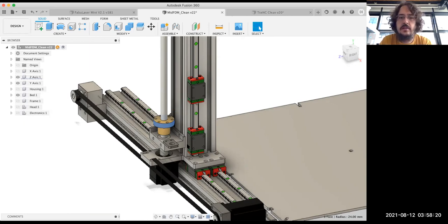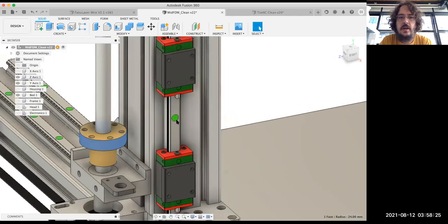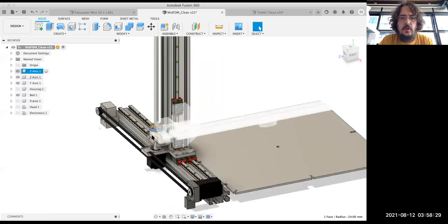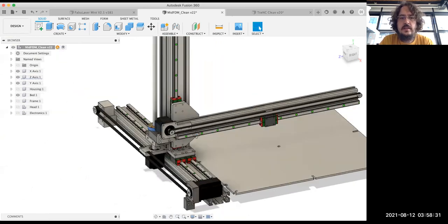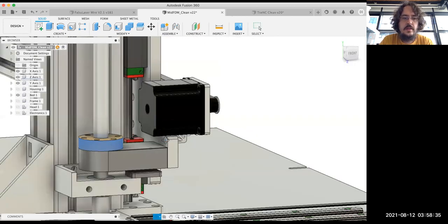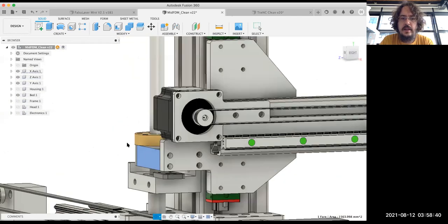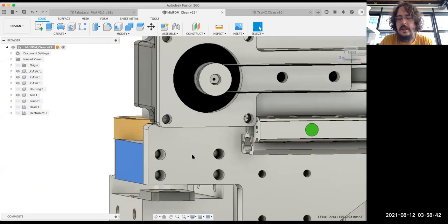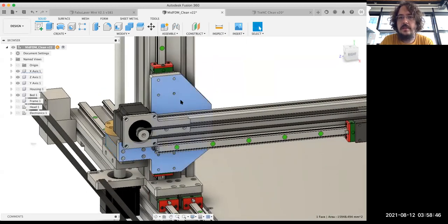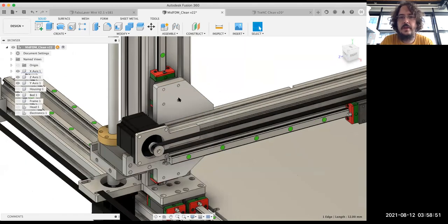And then they are quite straight and flat, and they have these rails where you can put T-nuts inside, and then you can easily attach and center the aluminum profile. So if we continue, the x-axis basically mounts on the z-axis, and it uses this CNC milled piece of aluminum that has some tapped holes inside here. And then this kind of triangular shaped CNC mill plate. This is, I think, 12 millimeter aluminum here.